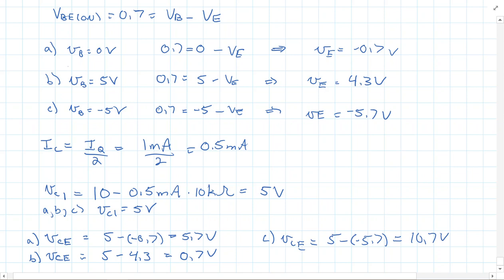Notice that if the input is 0, there's a voltage drop of 5.7 volts, so we would be doing 0.5 times that, which math right now, what would that be? Gosh, can't think of it right now. Let me pull my calculator up here. This is pathetic. 5.7 times 0.5, so 2.85 milliwatts if there's 0 volts in the common mode.